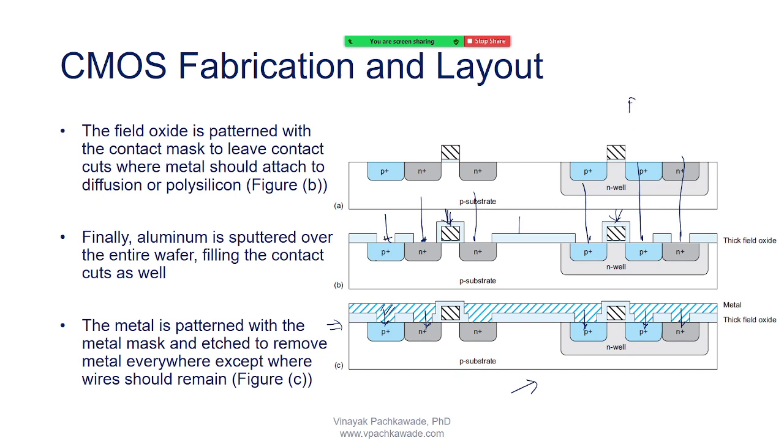When you as a PD engineer, or when you use some tools, there will be direct transistor layout cells ready-made available. For instance, you will have this N-well, and in the N-well you will have such a kind of cell. So that's already connected, so it means this is source and drain, and this transistor is, let's say, sitting in the N-well. So this is PMOS. So you will simply pick up this cell from the library, and then for the NMOS you have another, again the poly, source and drain. This is source, this is drain, this is the NMOS.